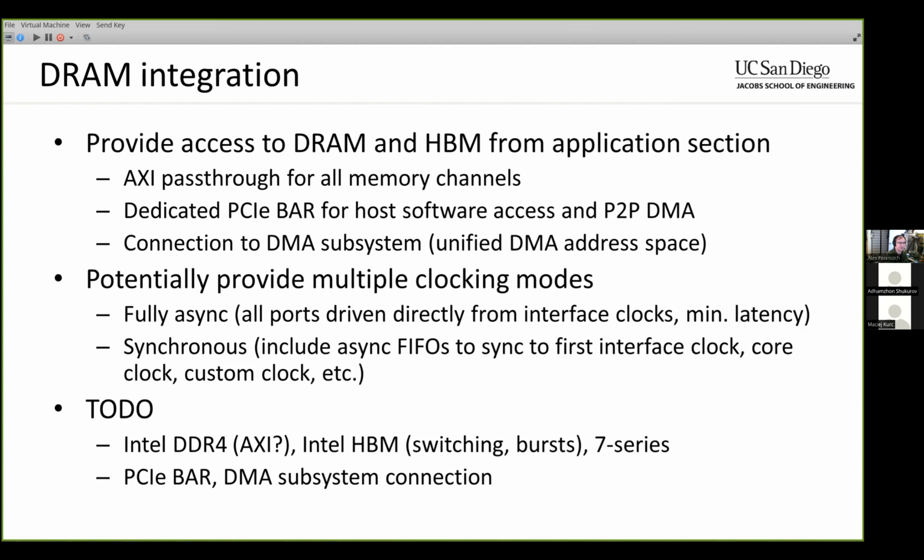And if we add any additional internal logic in terms of connecting this up to the PCI Express bar space, we'll do that with a small kind of AXI switch component that will run in the same clock domain as the MIG. So we won't add any CDC logic between the application section and the memory controllers. But this is not necessarily appropriate for every application. In some cases, you're not going to want to add a bunch of your own CDC logic. It makes sense to put all of these interfaces in the same clock domain.